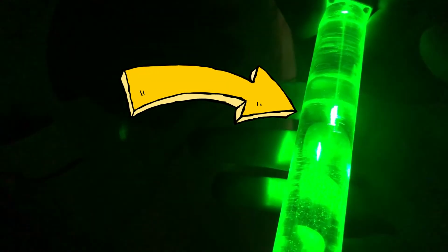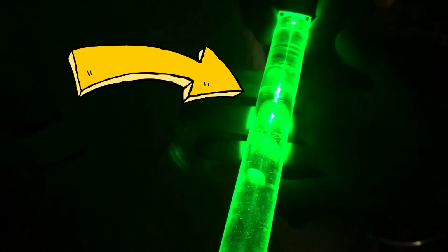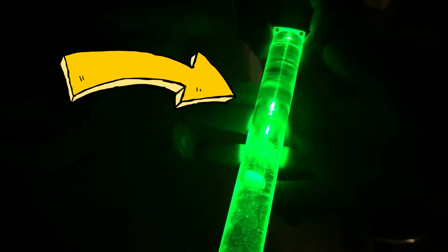The quality of fibers dictates the scattering losses. Every shiny spot observed corresponds to a defect. If the defect is on the surface and if the light's focus is there, a big amount of light will be lost in that spot. Even in a single mode, there is space scattering due to the defects present in the acrylic rod. When the fiber was observed from the top, there was too much scattering that appeared to be multiple signals in that segment. To observe the multiple mode, a white LED was used.